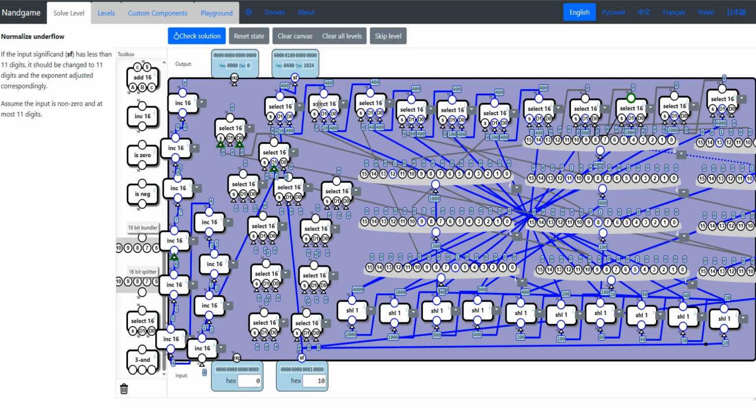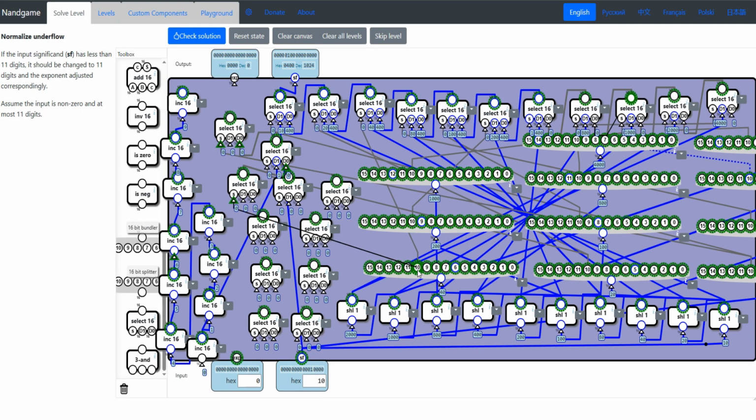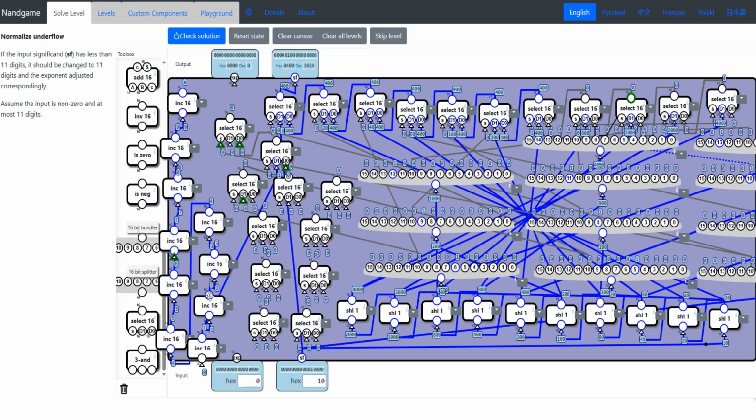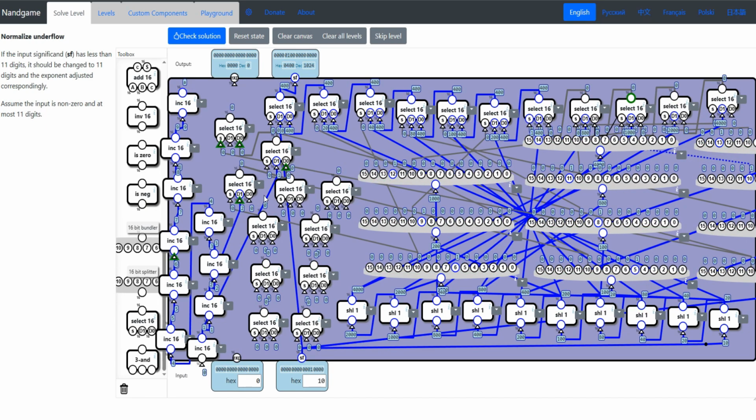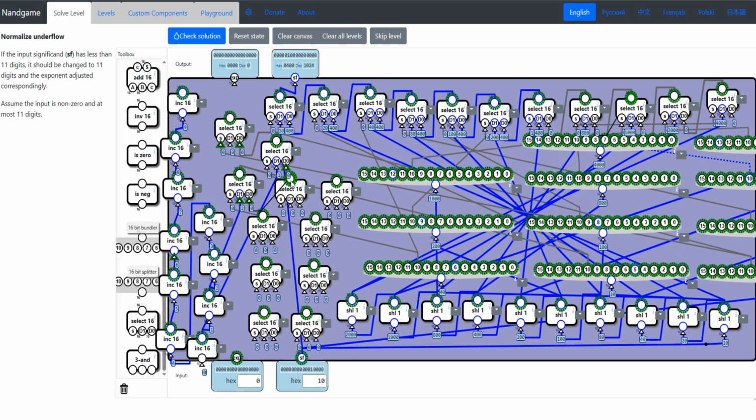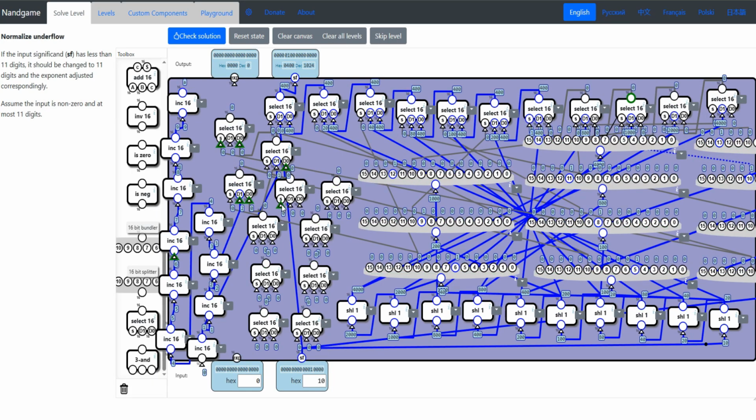Again, we're cascading just like we did before. We'll continue on. We'll hook up this D0 right to this. We'll call this our third selector here. Hook it up to our third bit splitter, the 10th bit there. If it's 1, we want to shift it over twice. We'll hook it up to the 2 increment. And if it's not, then we want to go to the next one here. All right, I'm going to keep cascading and hook them all up.